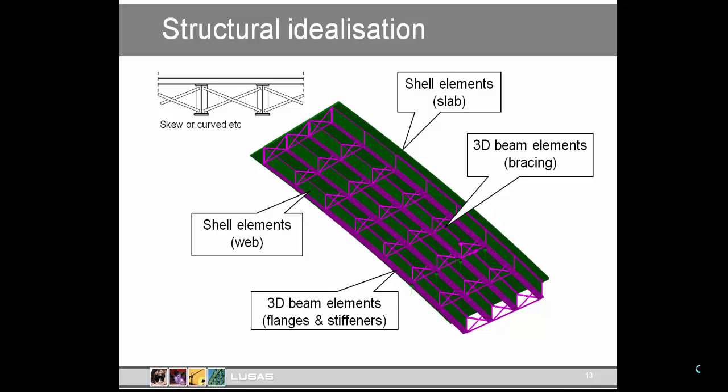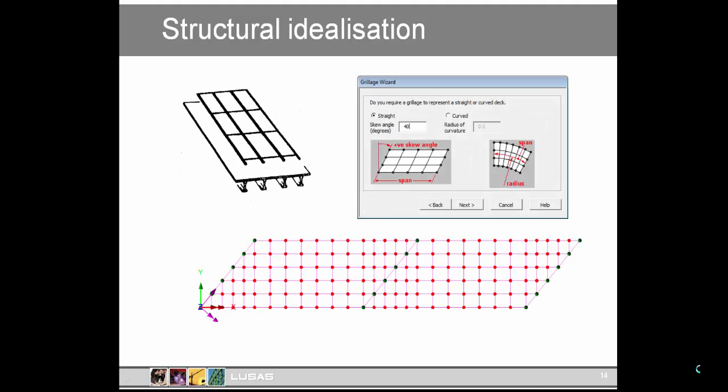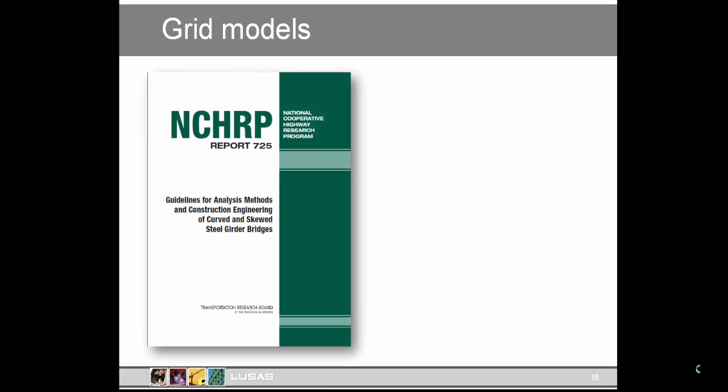I mention this because it's tempting to persist with our grid or grillage modelling approach, because we're familiar with it. We've got wizards which help us. It's tempting just to extend the idea into 3 dimensions, with the abutment walls treated as grids too. Well, we know there are some drawbacks of grillages.